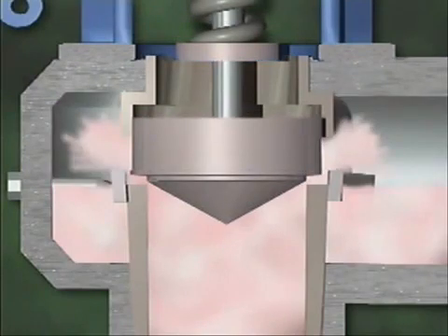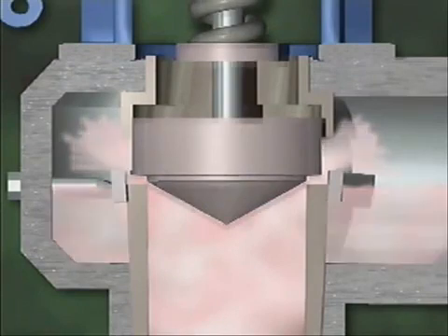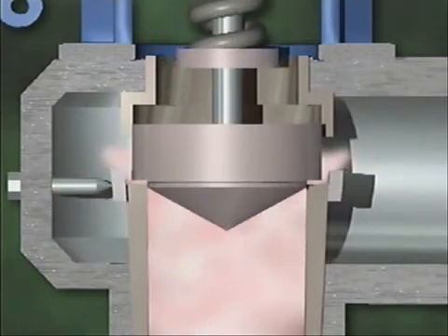As pressure decreases, the velocity of the escaping fluid also decreases. Spring tension begins to take over, pushing the disc down. The spring tension in a safety valve is preset, and it must be correct for the valve to operate properly. When the system pressure drops to the point where the valve popped open, 1000 psi in this case, the valve doesn't close, because the lip of the disc is still exposed to the pressure and velocity of the escaping fluid.